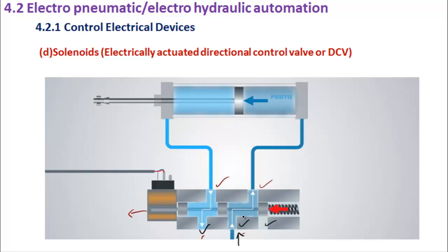But now, because of the movement of the spool, the pressurized air is entering this pipe. That means it is entering at the back of the chamber. And here, this is getting opened, because of which this particular piston will move in this direction. So it is for this particular motion of moving the piston here that we have changed the spool.